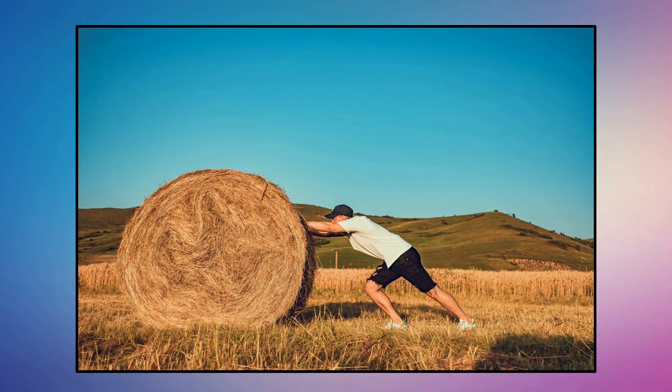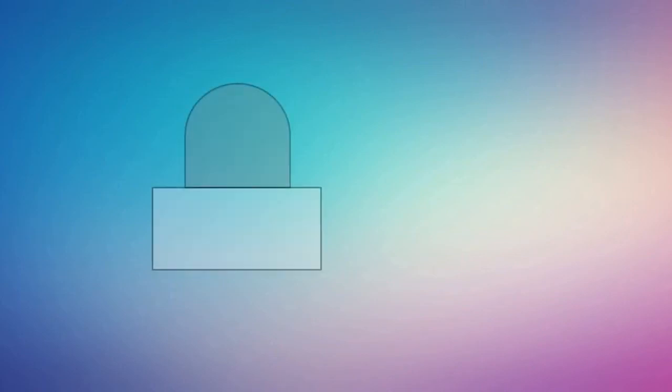Same is for the roller support. When we apply the load on the beam in the horizontal direction, the roller can't resist the movement of the beam in the horizontal direction. It only restricts the movement of the beam in the downward direction. If you want to know in detail about this, you can click on the link and check my last video. Next one is hinge support.